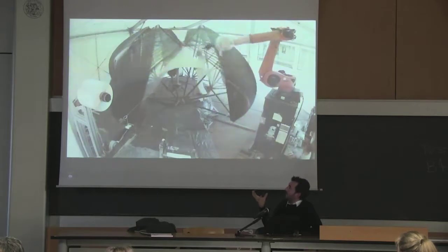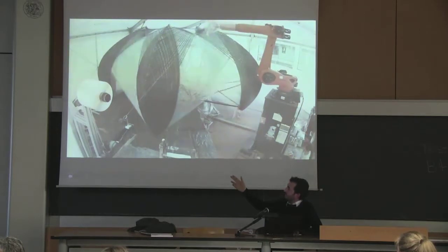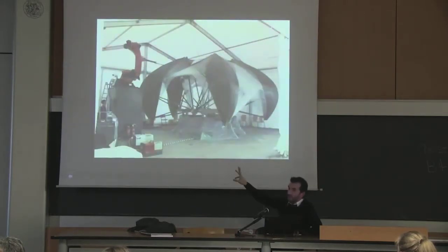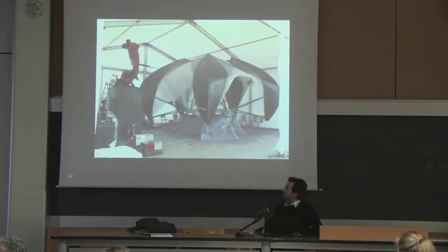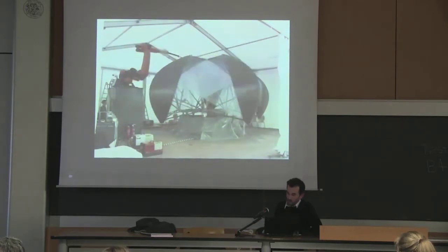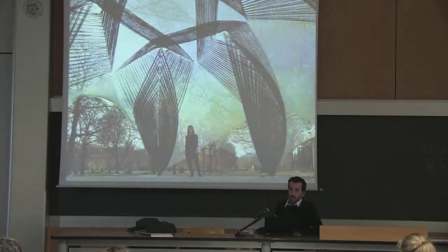So the glass fiber becomes the embedded mold onto which the fibers are applied in a resin saturated state. You see the fibers run through the resin bath, and then once they are applied, they slowly harden, so that in the end you can take the scaffold out and you end up with a very thin shell composite structure, which in this case consists of more than 90 kilometers of robotically laid carbon and glass fiber, but the shell is only 4 millimeters thick at the thickest point, which allows for quite an amazing level of transparency, especially when perceived from the inside.